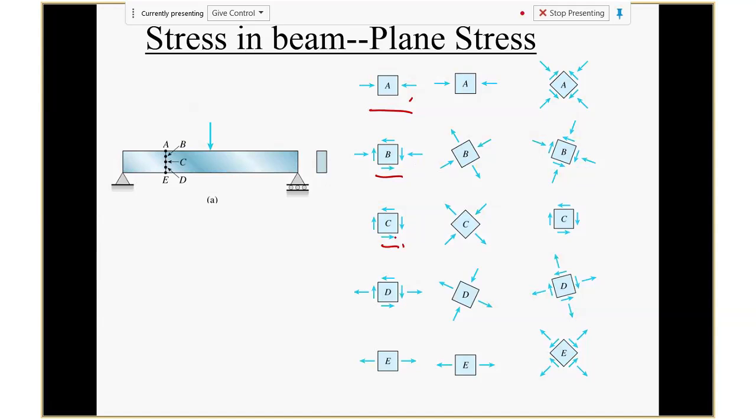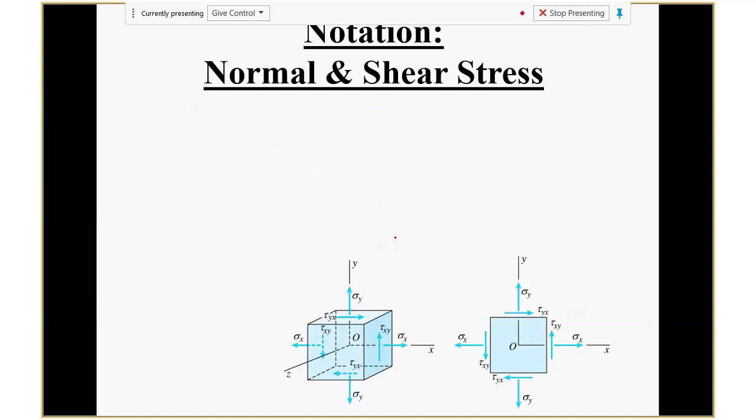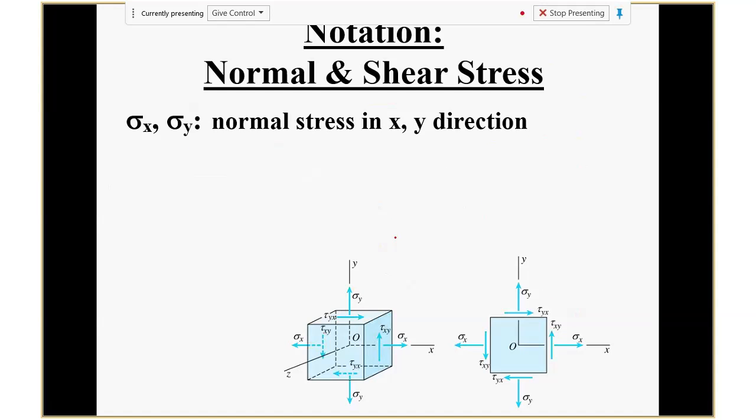So basically, when we talked about the beam before, we considered only the 2D structure. We don't consider a beam loaded this way and an up-down way. So we always talk about a 2D beam, and that is a perfect 2D plane stress example. So we already saw lots of examples. We just didn't mention it was plane stress. So now just to clarify, this is the condition we call plane stress, because there's nothing in the z direction, stress-wise.